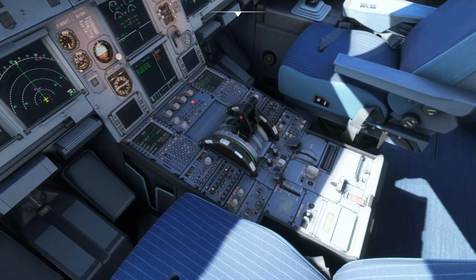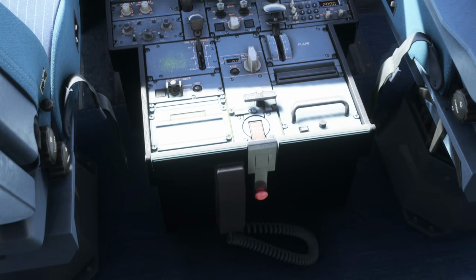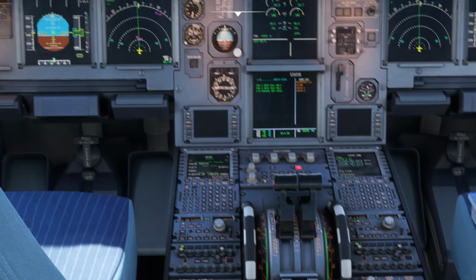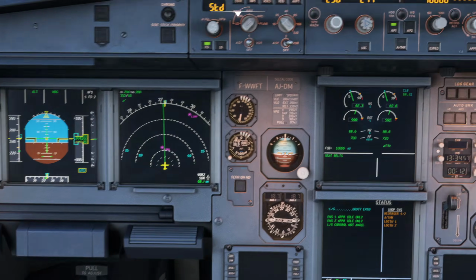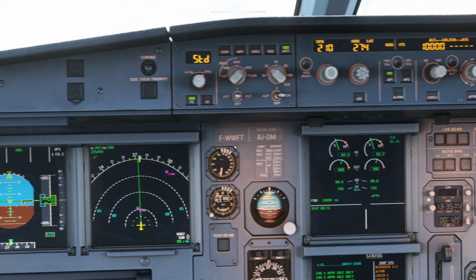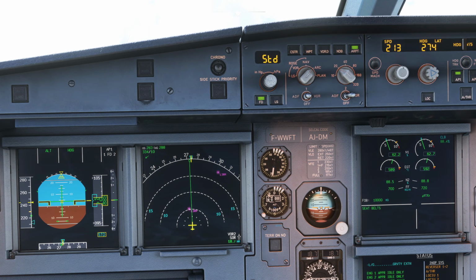Anyway, what I'm here to show you is that, of course, the landing gear can be extended by gravity, so you click down on the button on the Fenix to lift it. Let's get our speed back a bit. We can extend the gear at 250, no problem, but again, very noisy. The limit is 250, so we really would like to be a bit below that. Let's go to our green dot speed of, we'll just go over, let's do 230.